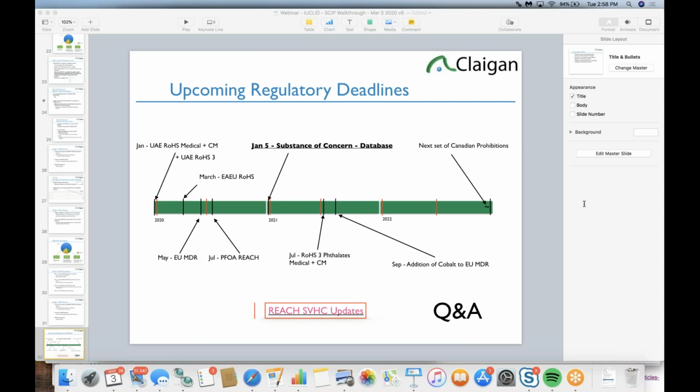So lead in the glass is not lead metal. It's a different CAS number, different chemical number, different EC number. Lead high temp solder on your components would apply, as would, if your product does not have to be RoHS compliant, use leaded solder, the lead solder.